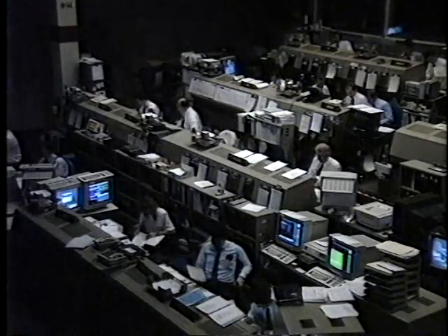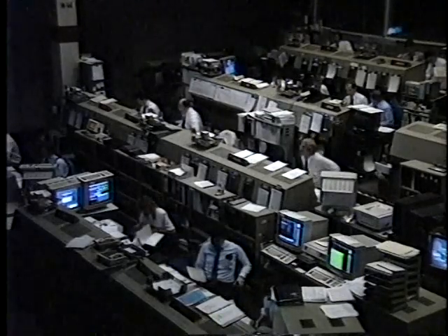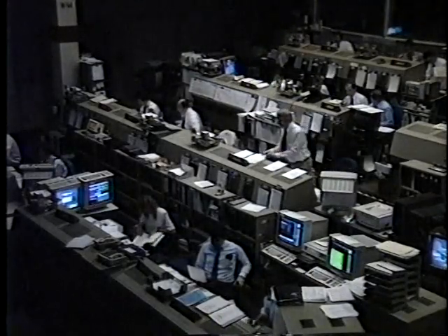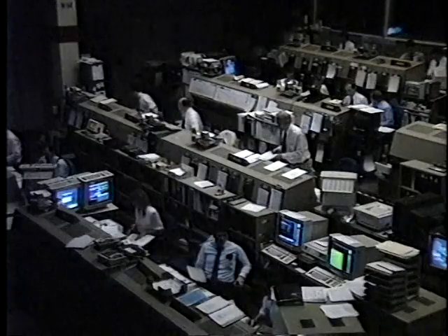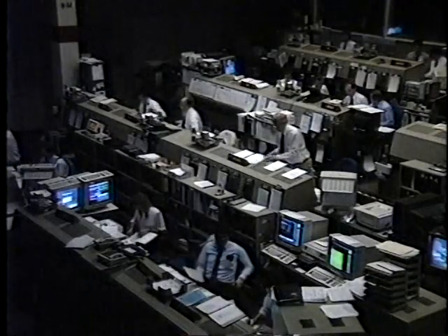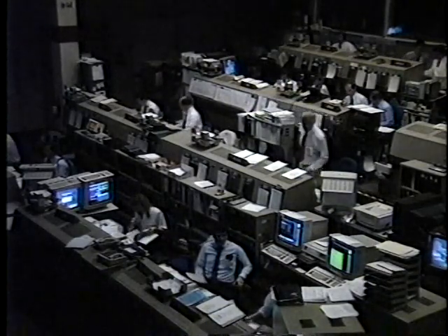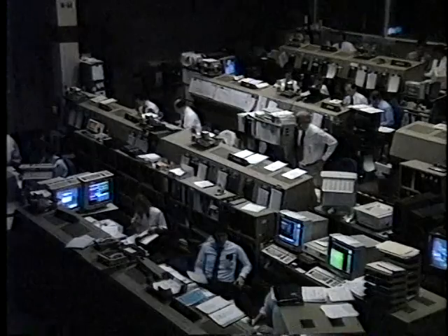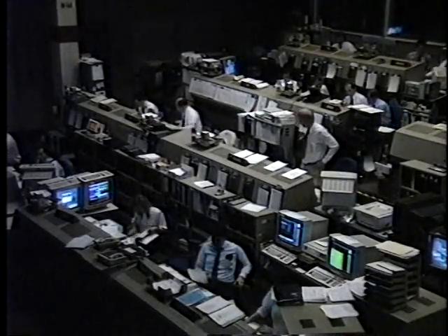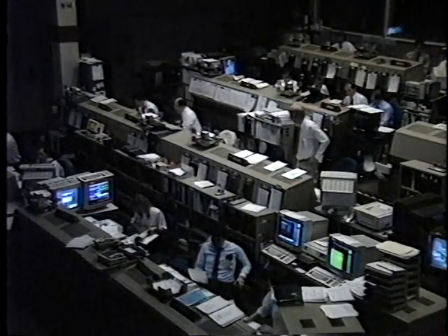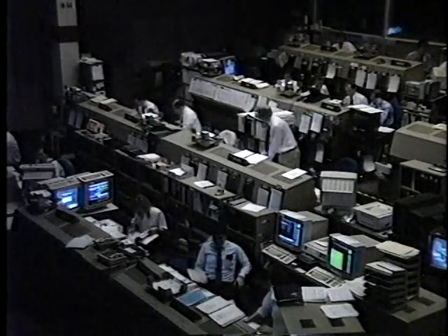Right now, the crew is pretty well occupied with getting their spacecraft squared away for extended orbit operations. They're in the early stages right now of preparing their data processing systems, the onboard computers. That is assigning them the new domain of software that they'll use, and assigning new channels between orbiter systems and the computers to make sure that all systems will be properly supported both by the computers and observed by the ground throughout the orbit operations phase of the flight.